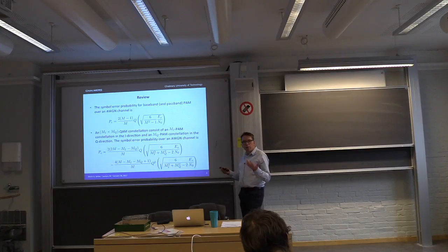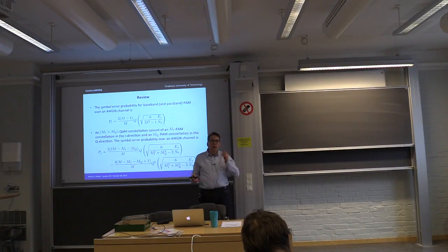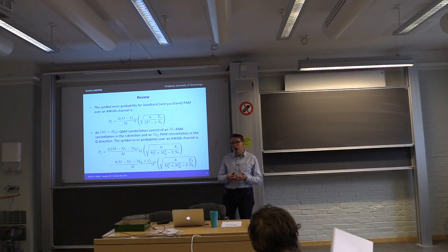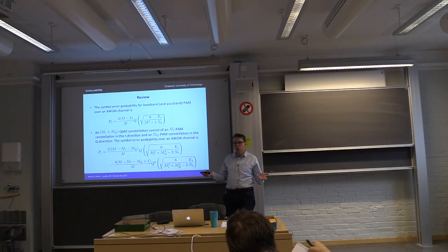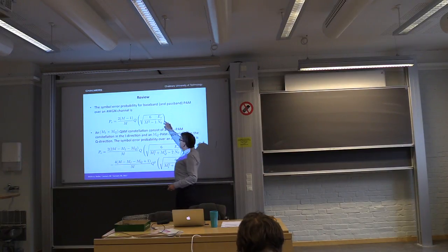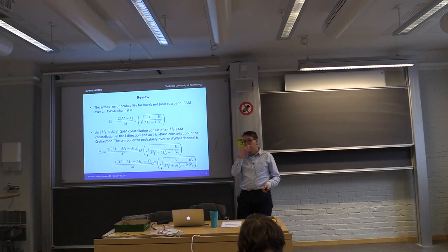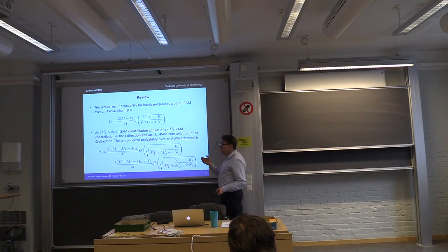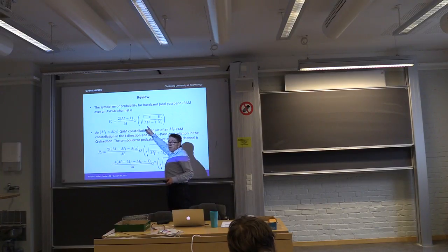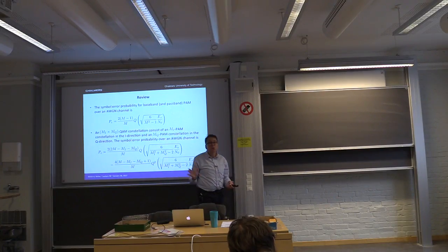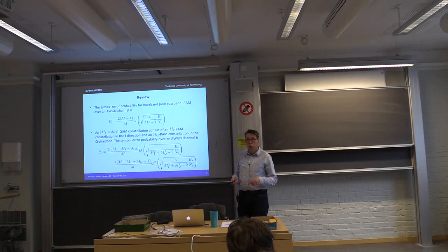And the overall result, one would say, is that the error probability goes down when Es over N naught is large, which is also known as the signal to noise ratio per symbol. As that increases, performance gets better. Another thing which happens is that when M is increasing and everything else is fixed, then performance gets worse.